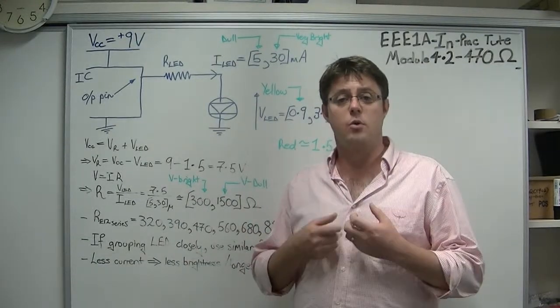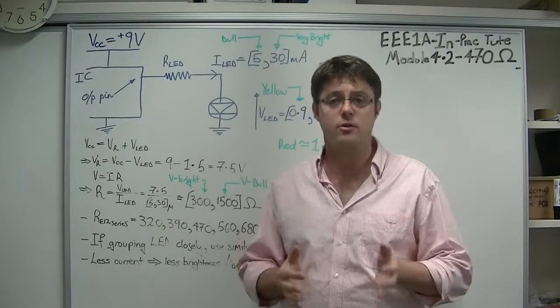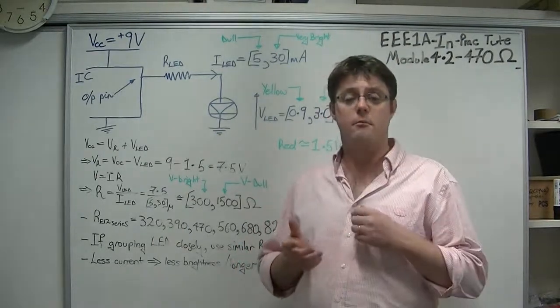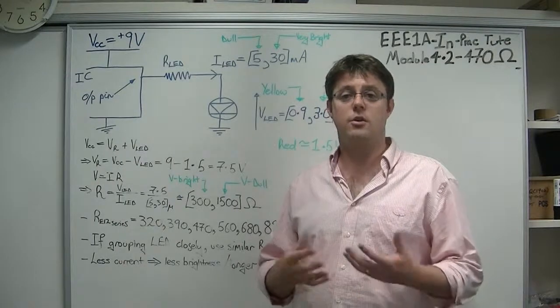Also you should know, the more current you push through an LED, the shorter its lifetime. And conversely, the less current you push through an LED, the longer it will last.